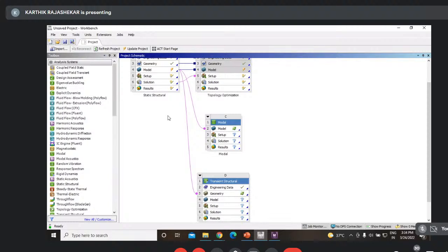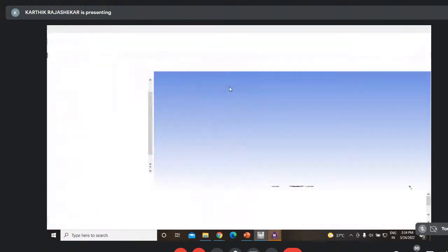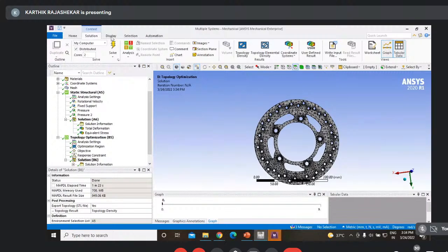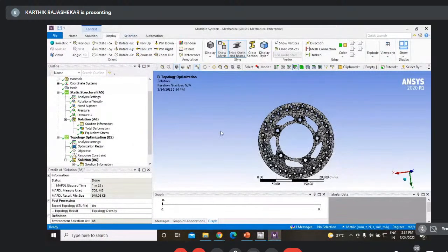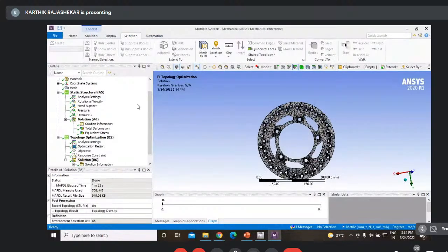As I said earlier, meshing plays an important role. Again, there are certain softwares. If you go to HyperMesh, HyperMesh has the capability of meshing the given geometry. Along with that, recently they have added analysis to it. There you can go for different types of meshing, either a tetrahedral mesh or any other type. Once you have generated a figure or a result over here, you can simply go for display, keep it in different views, or capture the result.